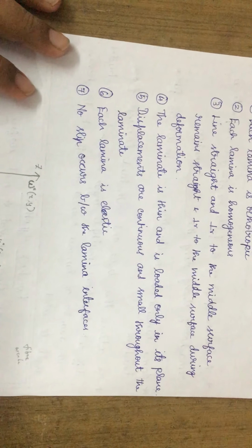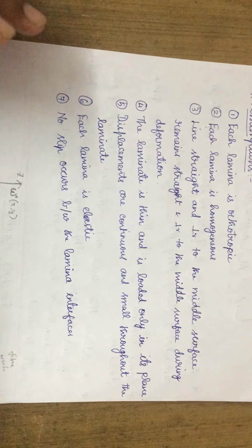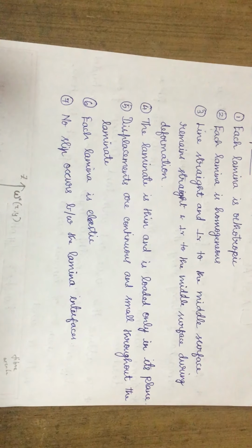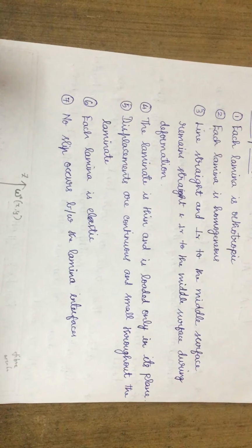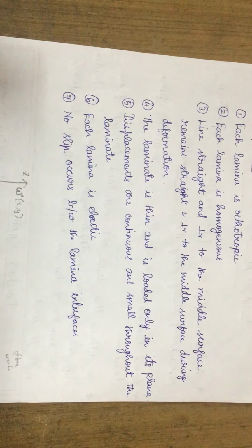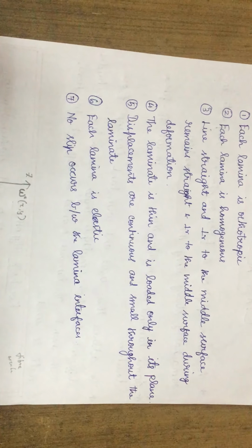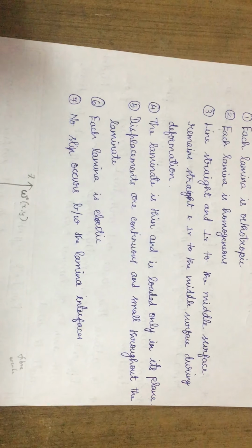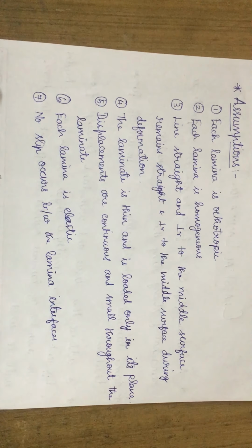Only very small displacements are considered, and this hypothesis is valid only for thin laminates as well as continuous small displacements. Make a note. This will not be suitable for thicker plates. This will be the basis for your derivation.